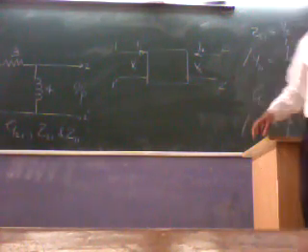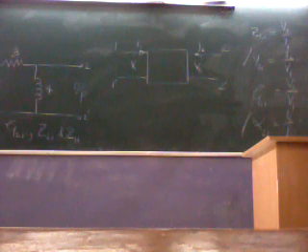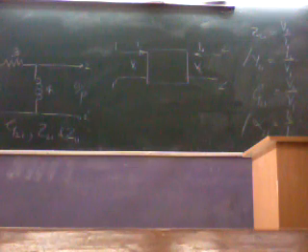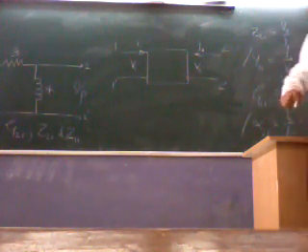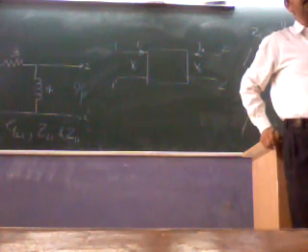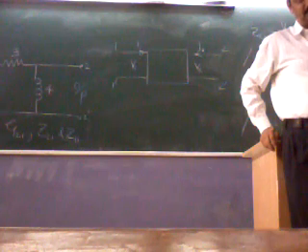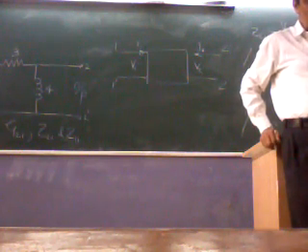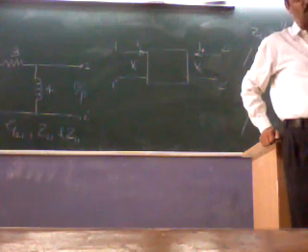Therefore, the ratios V2 upon V1, that is the transfer ratio G21, and the transfer impedance V2 upon I1, Z21, are defined independently for the no load condition also. Whereas the other two are zero for the no load condition.